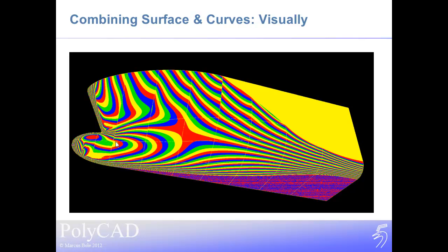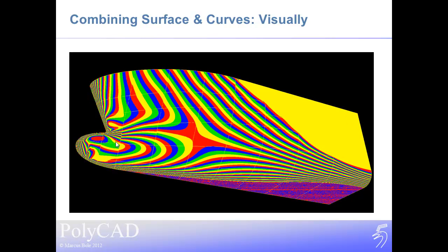I'm going to purely focus in this case on the flat of side to give a better illustration. So after about half an hour's work, this is the level of improvement that I was able to achieve. We've now got a much smoother surface around this flat of side. It's not yet perfect, but it's much better than it was. Of course, we can carry on and get the smoothness of surface by spending more time on it. But the nice thing about putting these lofted curves on top of the definition that generates our surface is that they highlight where our surface was unfair.